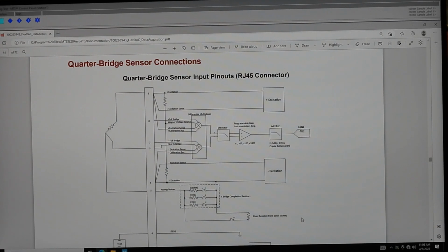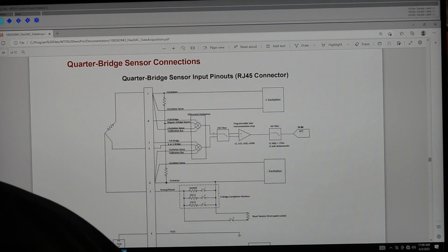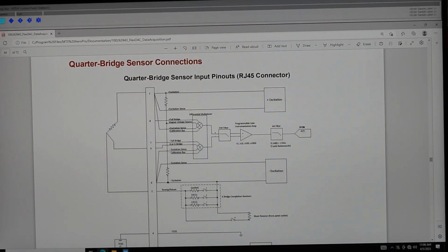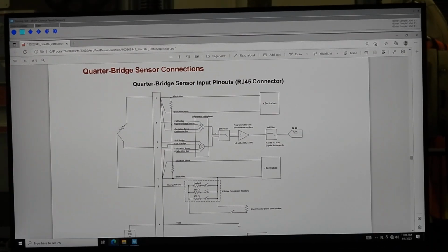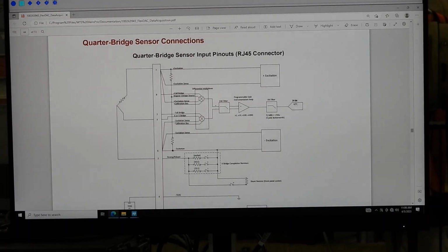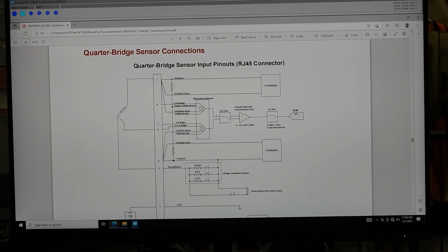Well, the one on the front is a 54 kilo ohm or something along those lines. 54.9 kilo ohm, for inducing an appropriate range of strain based on an assumed 350 ohm gauge resistance, I believe. So we can switch that out to something higher if we expect high strains.